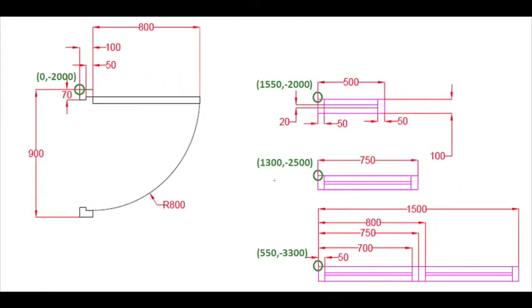Lastly, let us look at the doors and windows schedule. Now I don't have a problem with this except for the fact that I have to place the single windows. I put the 500 mm window at the bathroom, and the rest of the single windows I put at 750.